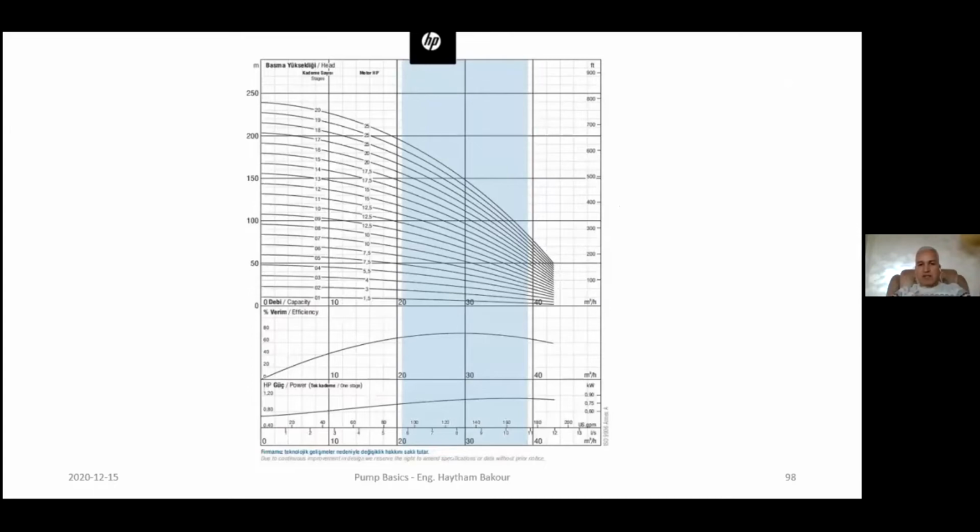In general, when we are trying to look for a pump, we go to the catalog and look at the flow rate. For the Grundfos series, I can see here 15, 30, 80, and we have a series of types of pumps. For those series, we can take the flow rate as 30.